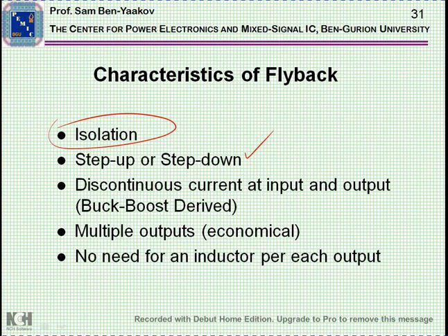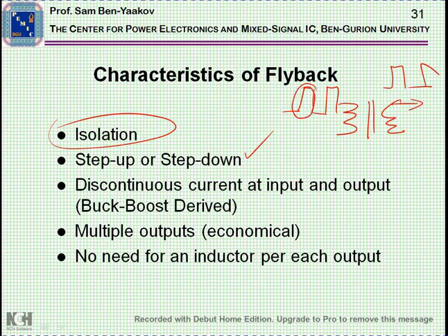A disadvantage is that if you look at the current at the primary and at the secondary, you see the current is sort of interrupted. It's not continuous. This is now the current coming out, because during the on time there is current here, during the off time there is current here. And this pulsation causes ripple and noise, so this is not a very desirable feature, but this is part of the characteristic of the Flyback converter.